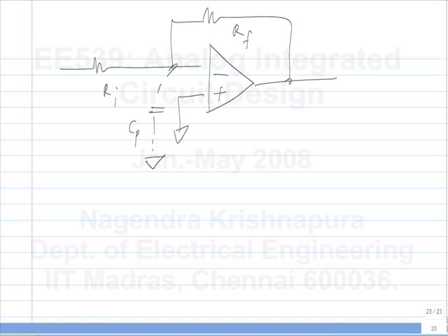Okay, now Cp consists of the input capacitance of the op amp. Once you choose an op amp, you can't help it. Okay, that is fixed. An important part of it is you have a metal track here. So these are all things that come only when you start building stuff. That's why I asked if anyone had built it. The metal will have some capacitance to ground plane. If you see how PCBs are made, there are tracks on one side and maybe ground plane on the other side, or some tracks close by and so on. So all of that will also add capacitance. So that you absolutely have to minimize.